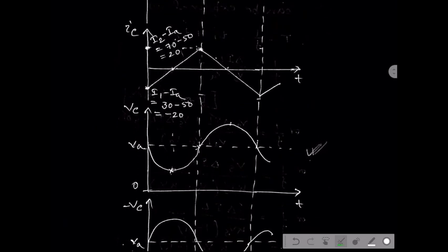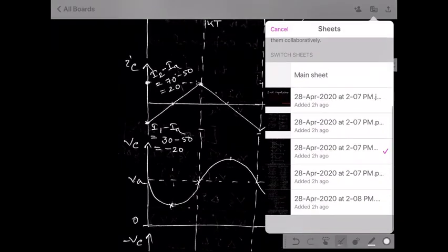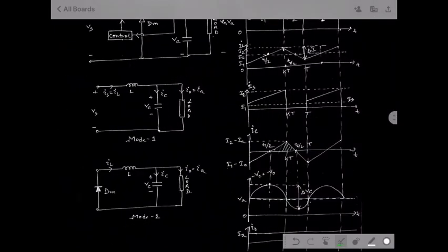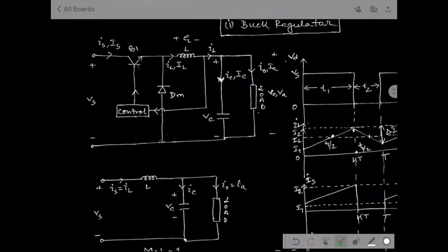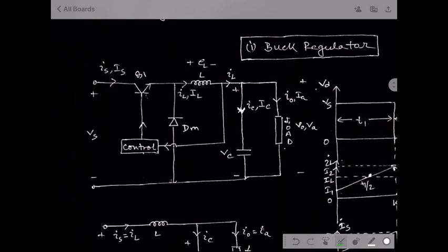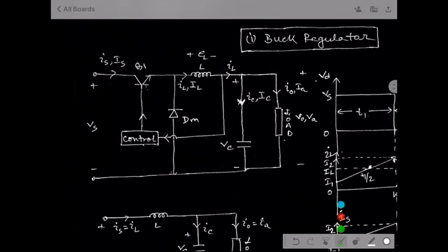See, now going to the circuit diagram first. See the circuit very carefully. We assume the inductor current gradually increases from its low value of 30 ampere to 70 ampere. It's true. And we assume the load always gives us a constant DC magnitude, that is 50 ampere. I just told you before.